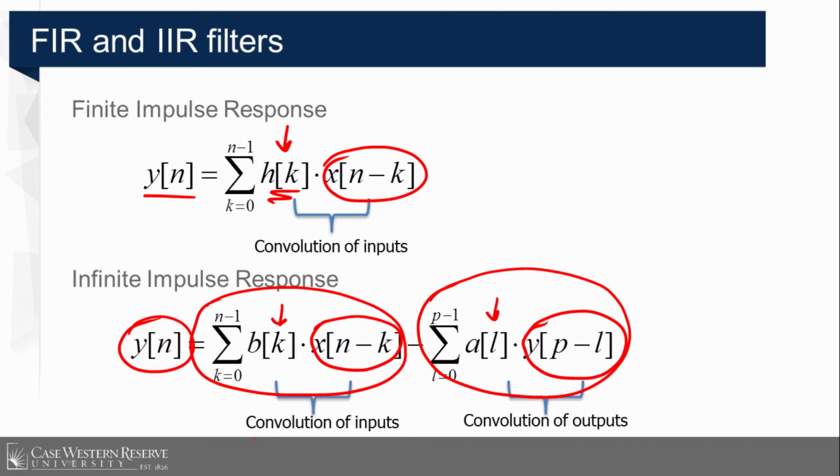And we call these filters infinite impulse response filters because here we no longer have these set values of coefficients that we're combining with our inputs to give us our outputs. We actually have some combination of coefficients on inputs and outputs combining together to give us our outputs.